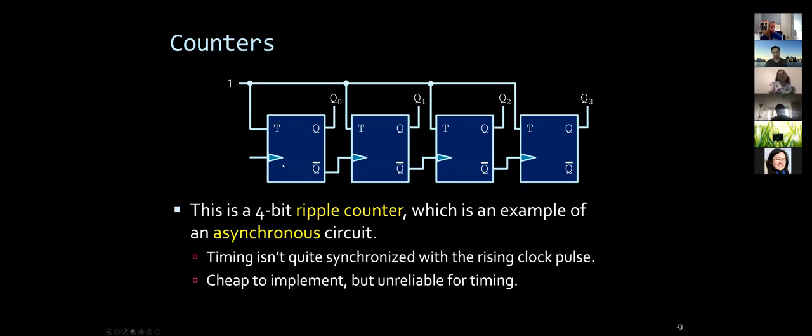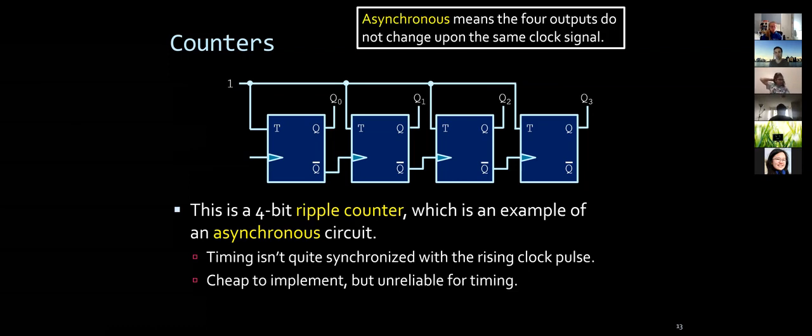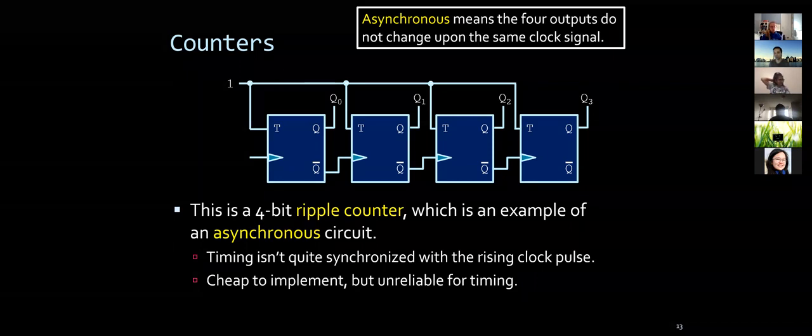We have all these guys here, 4 independent flip-flops. And what we do, we connect their NOT Q output as the input of the next one. So essentially, if you carefully look at what this thing does, it is going to try to do counting, right? Although that's not a good design, which I will explain in the next few slides, conceptually what the circuit is going to do is count.